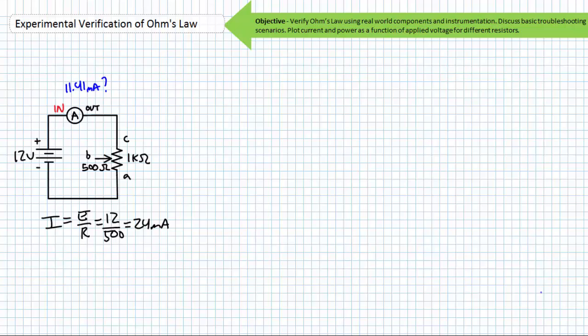Fix it. If the symptoms disappear, the case is closed. If the symptoms don't disappear, it's back to the drawing board. Troubleshooting might not be one shot, one kill, but only the most uninformed and stubborn of people let troubleshooting become a grueling battle of attrition. Your knowledge of basic properties like Ohm's law can cut out a majority of the labor. Truly half the time saved is simply the avoidance of checking and fixing things that aren't broken in the first place.